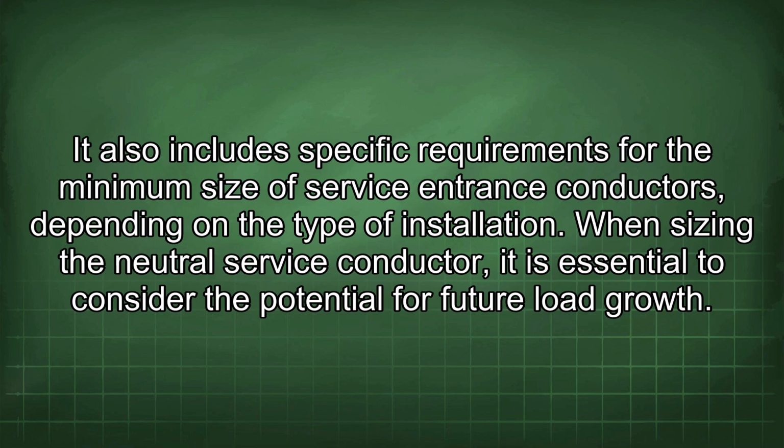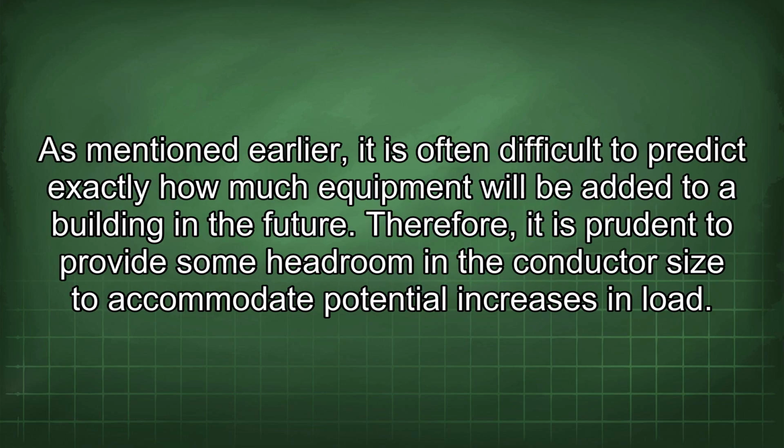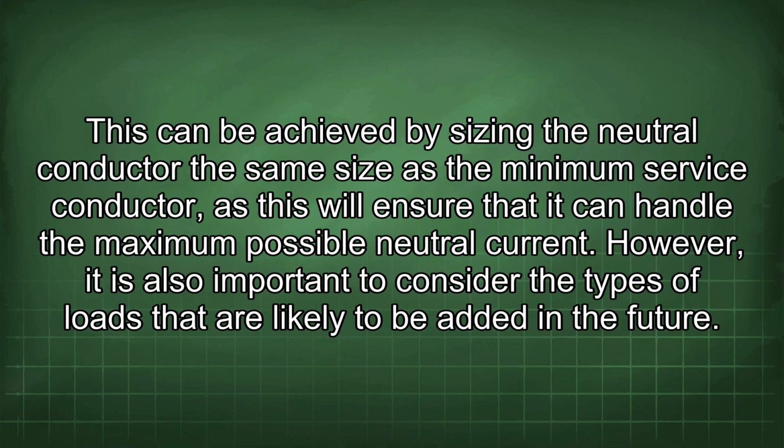When sizing the neutral service conductor, it is essential to consider the potential for future load growth. As mentioned earlier, it is often difficult to predict exactly how much equipment will be added to a building in the future. Therefore, it is prudent to provide some headroom in the conductor size to accommodate potential increases in load. This can be achieved by sizing the neutral conductor the same size as the minimum service conductor, as this will ensure that it can handle the maximum possible neutral current.